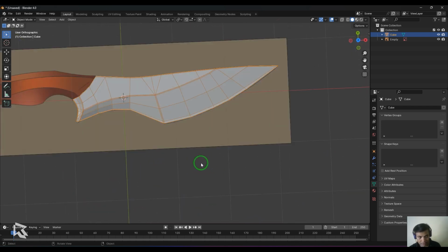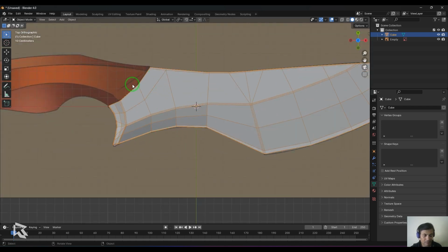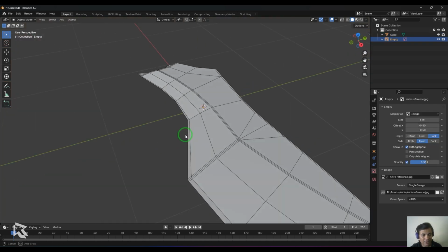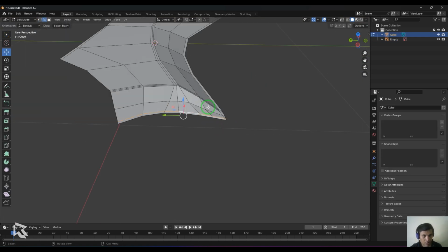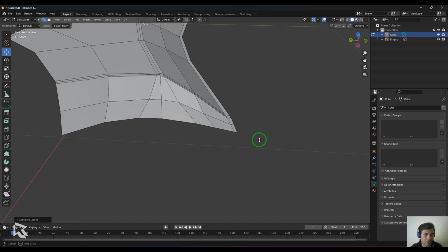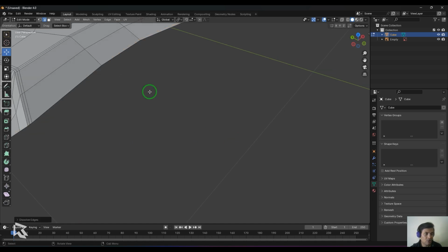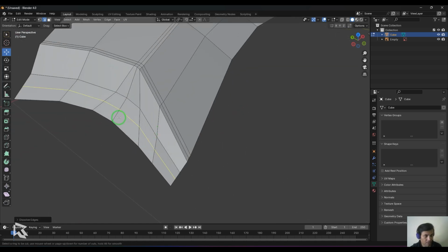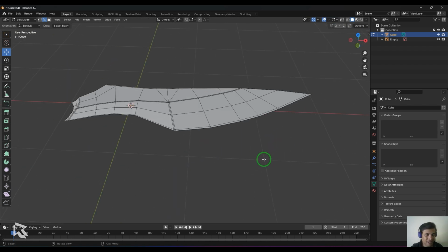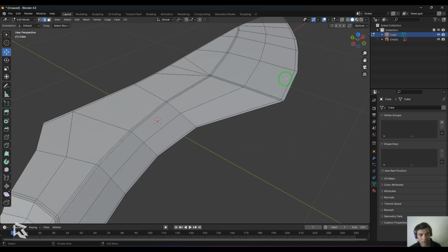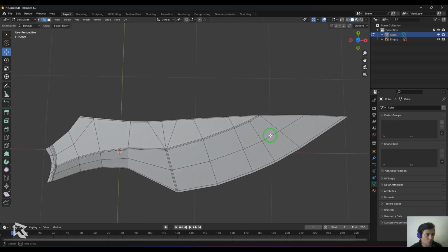Now what's left in this particular model is the bridging of this thickness on this side and on the opposite side. But how do I do that? Okay, one thing I would like to do is I select this edge, and then delete, dissolve edge here, and use dissolve edge. Now I'll add the loop here, which will generally respect the slope of the blade. So that's one thing which actually makes the model better in this corner of the model. Okay, so all corners got their lines.